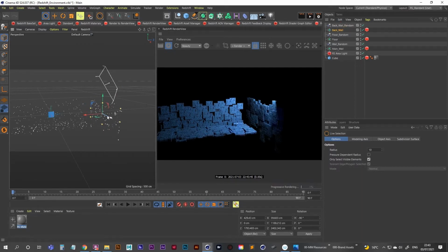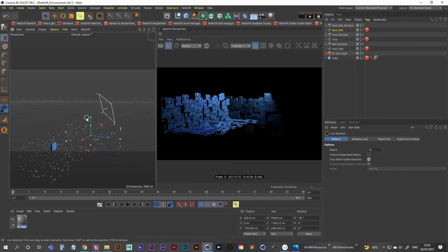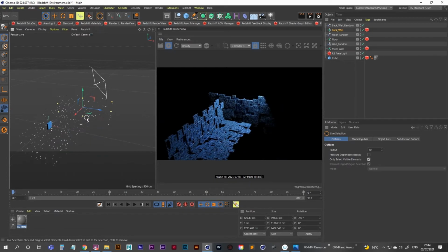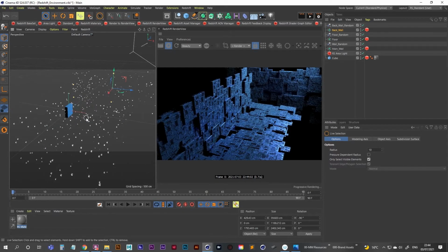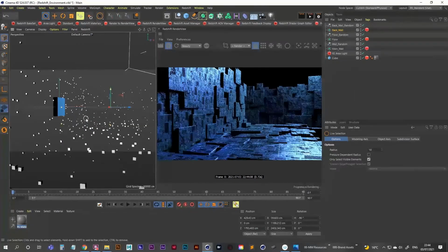And then I want to jump back to the camera angle I was just at. I haven't set up a camera yet, so what I can do is hold down Control Shift and hit Z a couple of times on my keyboard until it undoes each of the camera moves that I just did. So I'll be able to hop back into the camera view that I was at a second ago. There it is.